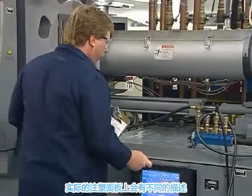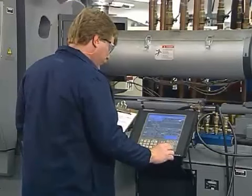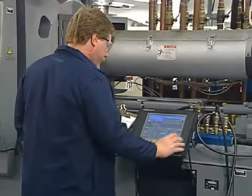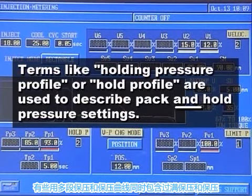Molding machine makers use different terminology on their controllers to describe these phases and pressures during a molding cycle. For example, many controllers use terms like holding pressure profile or hold profile to describe the pressure settings that both pack and hold pressure on the cavity.